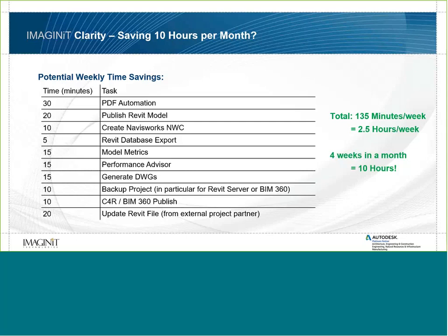Generating Navisworks files. It may not take 10 minutes, but let's say you need to generate the Navisworks file for project stakeholder X. That means I need to go to my computer, launch Revit, wait for Revit to finish launching, open the Revit file, wait for the Revit file to finish opening, publish to NWC, wait for the publish to finish, then close out of the model. That entire process, beginning to end, is pretty easily in that 10-minute range, depending on your files. There's all sorts of variables through here, but I don't think that these numbers are all that unrealistic.